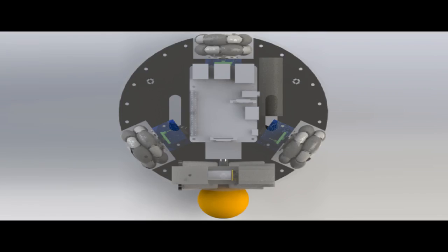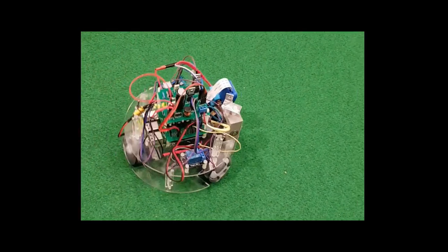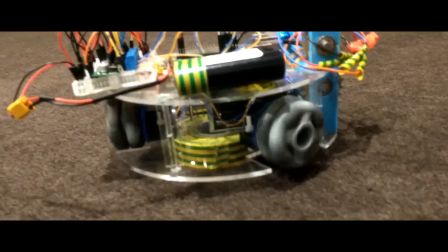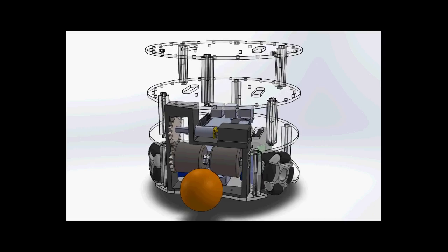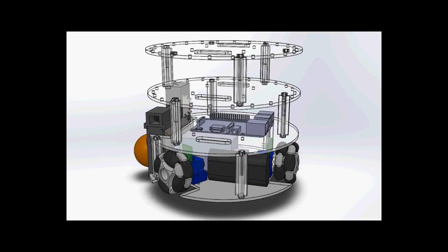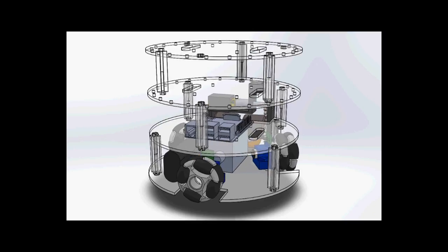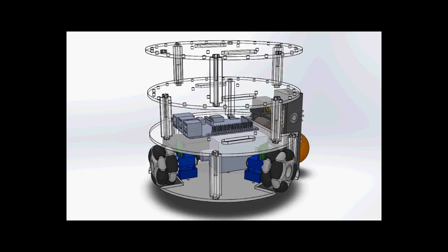Include an omnidirectional drive system with 3 wheels that allows the robot to translate across the field at any angle without changing its heading at speeds over 0.5 meters per second. Motor power and control is from 3 small motor drivers that have been integrated into a PCB that fit directly onto the Raspberry Pi. The subframe is designed with a modular approach that allows easy customization of parts. An example of this is the travel height of the robot, which simply requires new 3D printed mounting blocks.